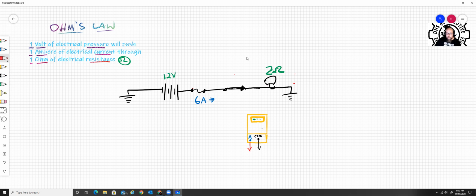Keep in mind, you must keep the amount of amperage that you're going to measure with a meter by itself less than 10 amps. Not 10 amps, less than 10 amps. So 9.999999, you're okay. At 10 amps, the internal meter fuse will blow. This is its circuit protection. So when I want to measure the current flow in this circuit, generally speaking, anywhere I measure it in the circuit, I'm going to measure that flow. The 6 amps is present here, here, here, here, here at the light, after the light, and way over here, okay?